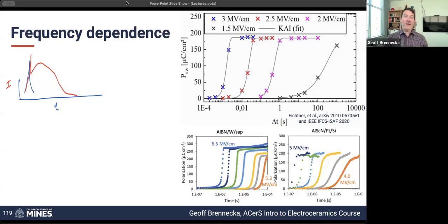So you can take advantage of that by just making that same measurement in the same polarity a couple of different times. So the very first time that you apply, let's say you have a material that's poled in this direction, and you apply a voltage that is going to want to switch the polarization down.